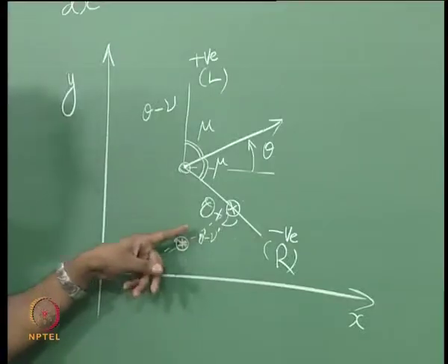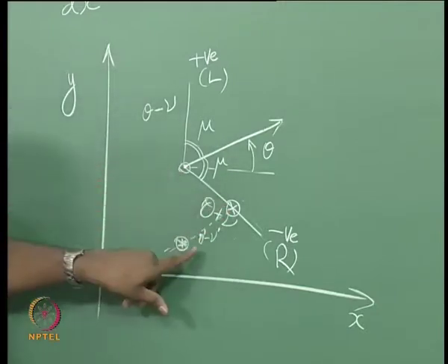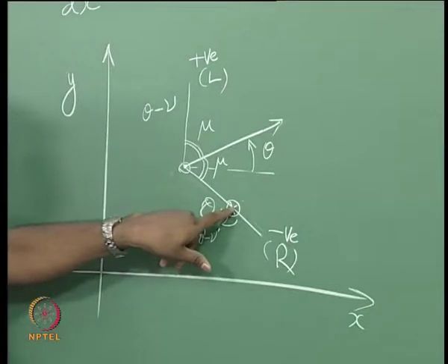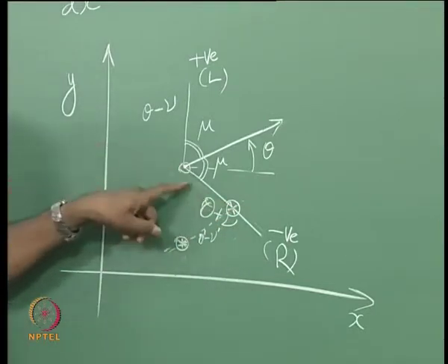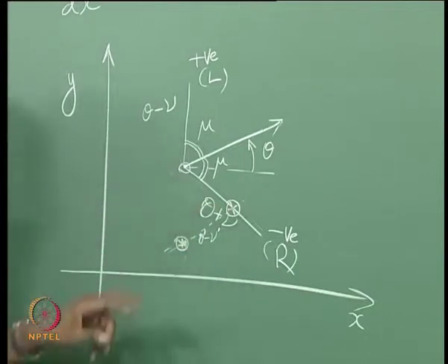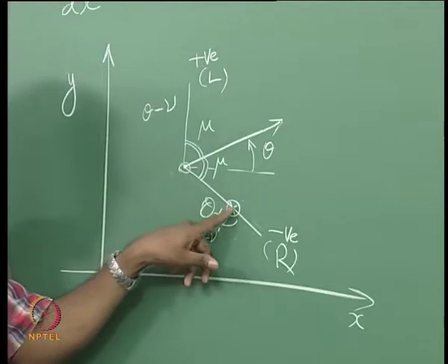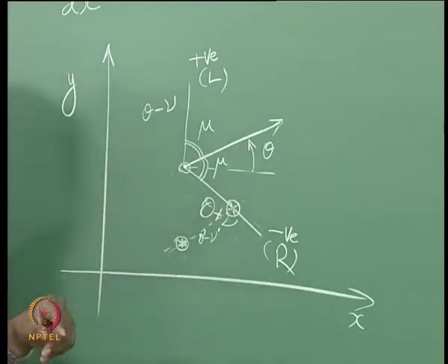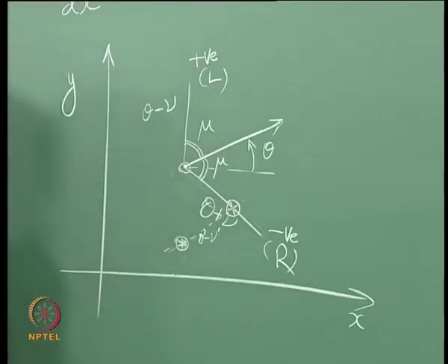and I am going to say this is going to set a condition on the difference between theta and nu on this point x, while this is going to set the summation of theta and nu at this point. Summation and difference will now be fixing the exact value of theta and nu at that point. Okay. That is how we can calculate another point on this flow field.